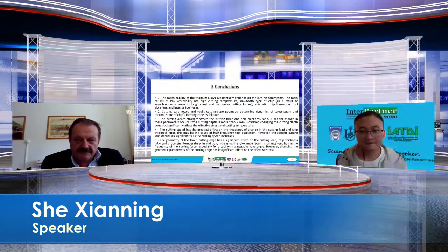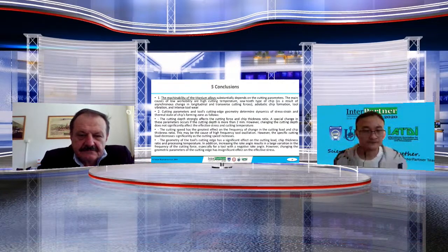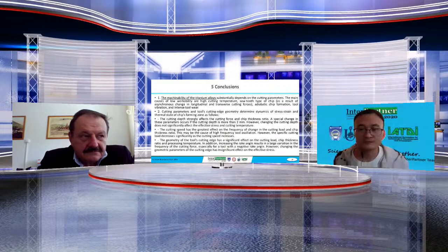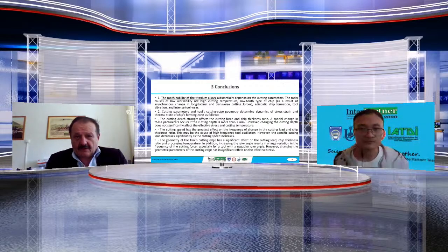Next, I'd like to add a little explanation for this, because I am a co-author of this research. Titanium alloys are very perspective and very interesting materials for operation, but for machining, this is a very, very difficult material. There is a lot of different scientific work to explain the processes, but we still can't finally understand why we receive the sawtooth chip, because there are, I know, 3 different theories, and everybody says theirs gives more exact results.